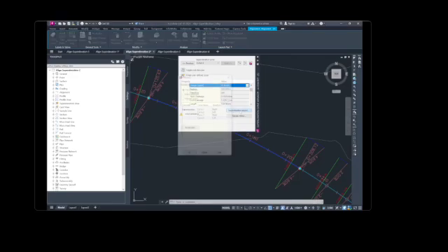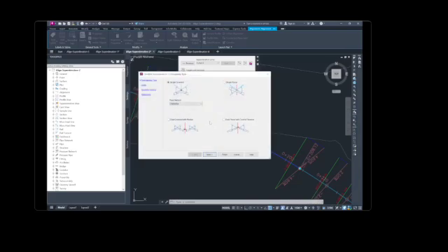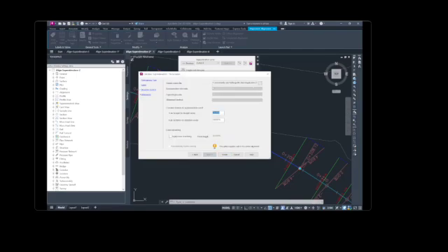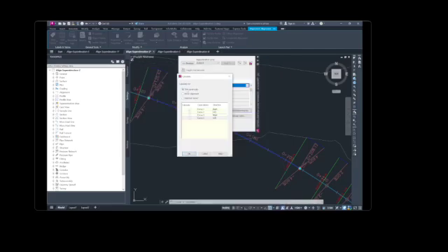Now we're going to calculate superelevation for an individual curve. Click Superelevation Wizard. The Calculate Superelevation dialog box enables you to select which curve to recalculate. Select This Curve Only and then click OK. Click Next. Then in the Calculate dialog, select This Curve Only and click OK.